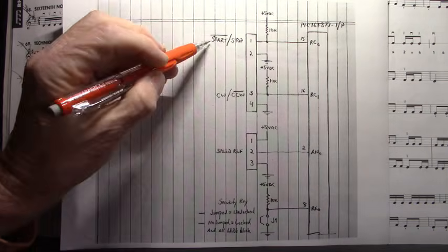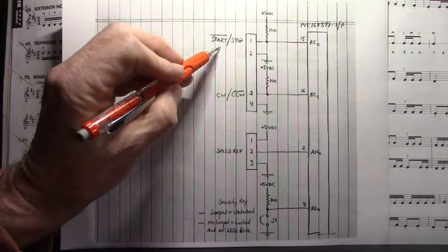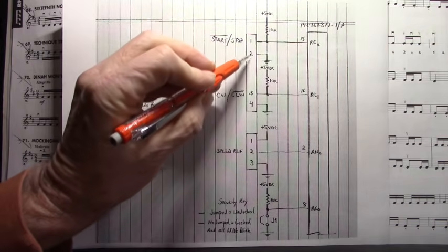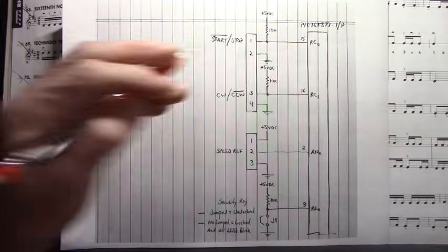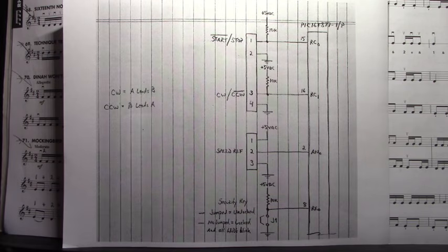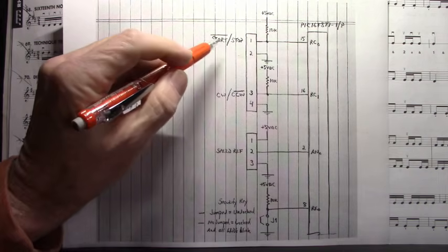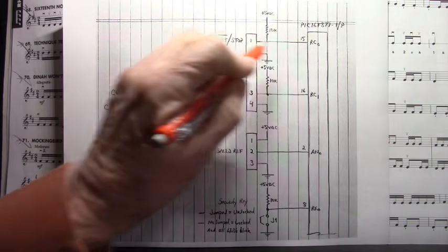Now, that's the start-stop circuitry without an optocoupler. So to start, we pull pin 1 to low, pin 2 ground, and that applies a logic 0 to port C0. And that output, that Hall effect encoder output, will be enabled. It will start to run. It will start to rotate that simulated encoder or that simulated Hall effect, or both. And with this input open, we have a logic 1 right here. That output would stop.